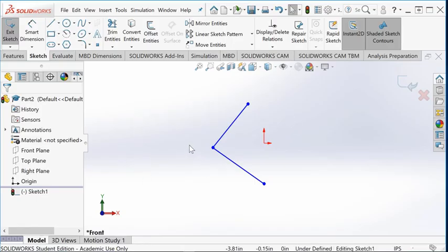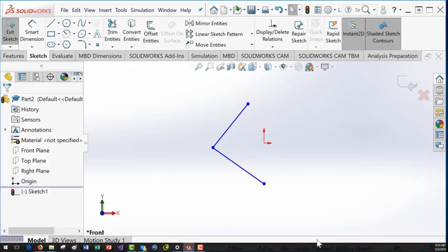And right now we are in sketch editing mode. There are a couple of cues for that. One, on the feature tree, there is a bar, and underneath the bar we have Sketch1. This is a new feature that is under construction because the bar is above it, and it has a minus sign. That is because the sketch is underdefined.